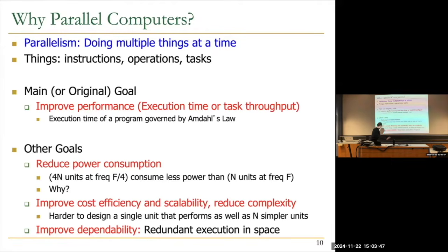Not necessarily linearly, but yes, certainly. Well, I don't want to talk about Dennard scaling, but that's not a bad question. Basically, you can see it, right? CV squared F. Dennard scaling is a technology scaling law that used to hold in the past. When you reduce the size of a circuit, you could reduce the voltage associated with it.